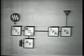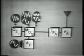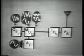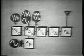When we modulate it with an audio frequency, the two signals are mixed together in a balanced modulator, which is designed to cancel out the carrier and produce only the two sidebands, the upper and the lower. We then insert a filter which will pass only one of the sidebands, and of course we can select either one, and we'll reject the other one. Thus we have only one sideband to be transmitted with all of the transmitter's power.